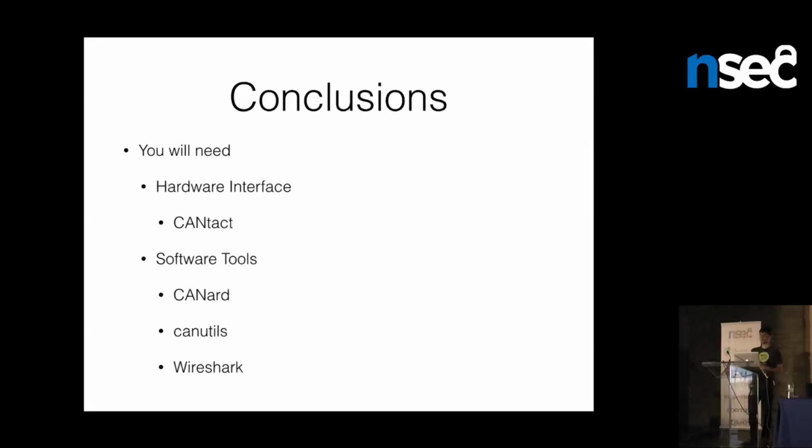And then the software side, you have all sorts of stuff, but for the open source stuff, there's the library that I've worked on, and also some others. There's actually a Ruby library as well, if you prefer Ruby, that does CAN. There's a lot of different languages. People have kind of hacked some stuff together. There's can-utils, if you want to play around with that, you can actually install it on Ubuntu, and using the vcan driver, you have to modprobe vcan, but once you get that up and running, you can send messages around in memory, so you can play around with these tools without actually having a car, without having a hardware interface, if that's something you want to play with. And Wireshark, you can also connect Wireshark to anything that's running and just watch, which is very useful.